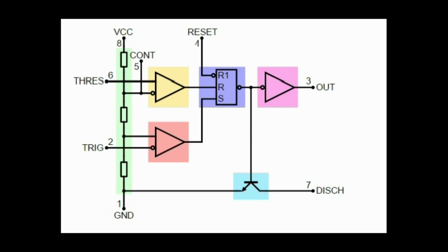The 555 can be used as a simple ADC, converting an analog value to a pulse length. For example, selecting a thermistor as timing resistor allows the use of the 555 in a temperature sensor, and the period of the output pulse is determined by the temperature. The use of a microprocessor-based circuit can then convert the pulse period to temperature, linearize it, and even provide calibration means.